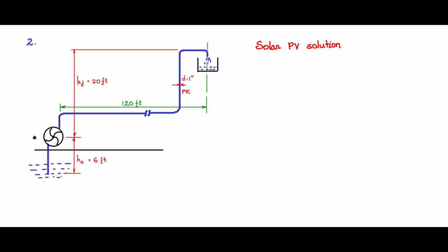driven by a motor, and that motor is not actually powered from the 230 V mains, as in the earlier case when we said that probably a single phase motor will be driving this pump. Let the motor which is driving this pump be a DC motor, and let it be directly connected to the PV modules. Let there not be even a battery. You will see that the solution is so much more advantageous, because instead of storing energy as chemical energy in the battery, we can store it as water at a lifted potential, pumped hydro.